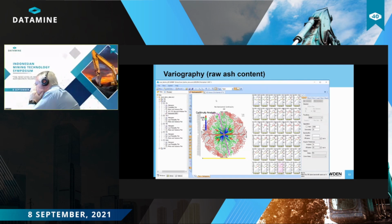So when trying to determine the direction of maximum continuity, all of your knowledge about the deposit should come into play. But if we look at this variogram fan, we're going to conclude in this example that our maximum direction is towards 345 degrees, as indicated by the green, the preferred direction of the green contour lines.